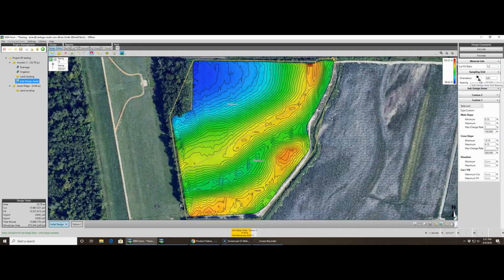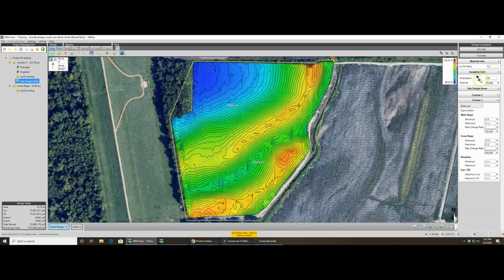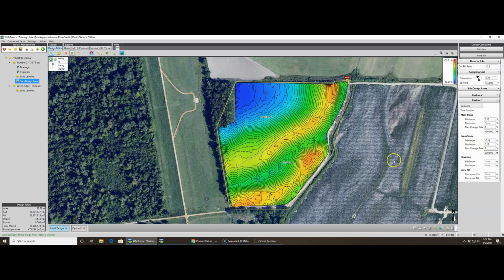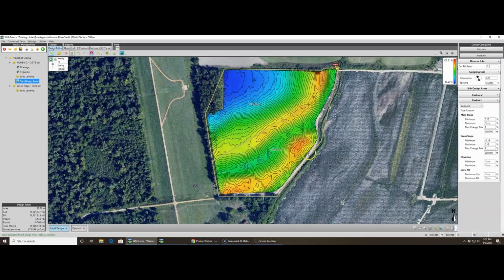And then the positive side will be this way. So it's left and right. So I don't want any more than 1/10 to the left of the line. I don't want any more than 1/10 to the right of the line. But since our orientation arrow shows this way, then we'll have to put in a negative to get that to calculate correctly. You could say, well, why doesn't it do left and right without the negative? Well, I wasn't on the design team, so it's just the complications of designing a program like this.